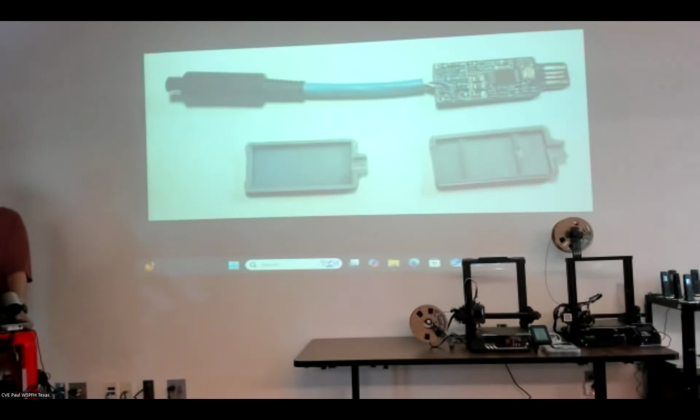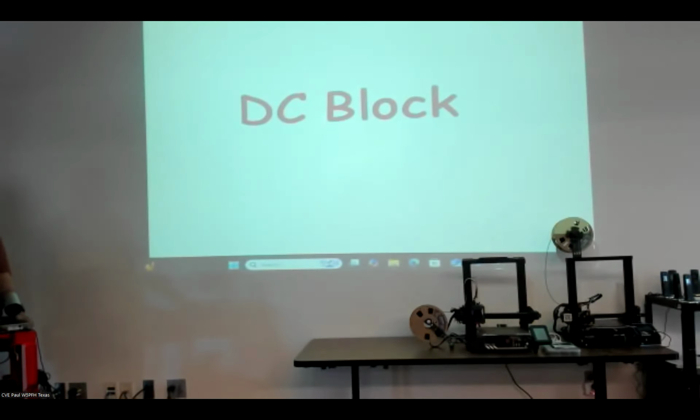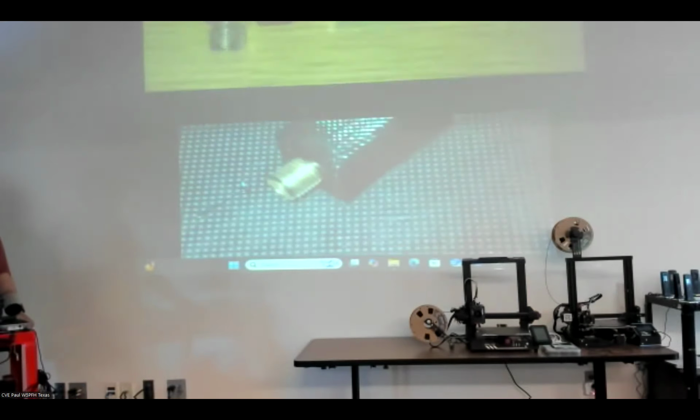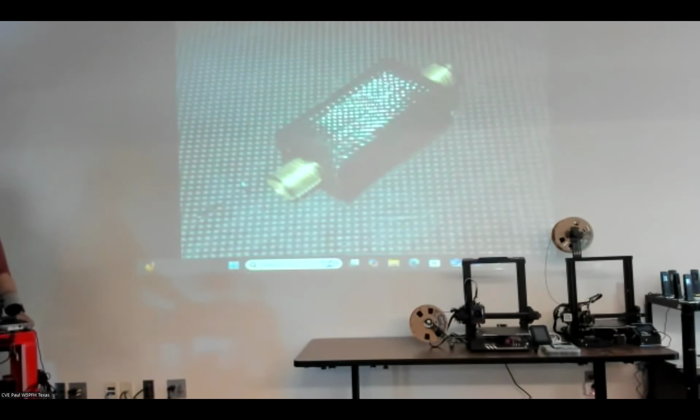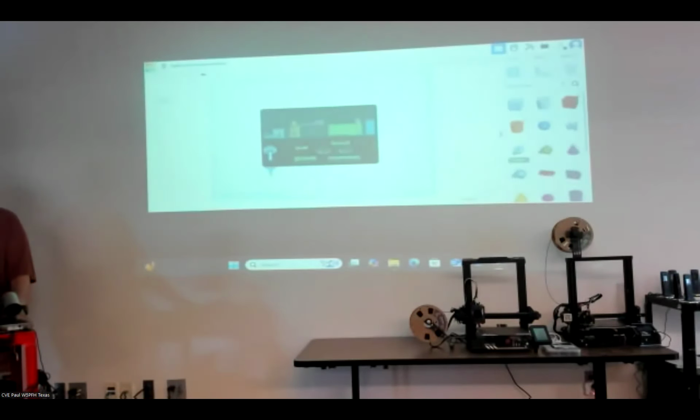It's having that extra glass filament in it. Coke bottles and things. Yeah, it's just having that extra additive to it. And sometimes it works great, and other times it's stringy. It's very stringy. Like, I was talking to Steve before the talk. Every time I print PETG, before I go to another filament, I change the nozzle. I always have gumming issues switching from PETG to PLA or anything else.